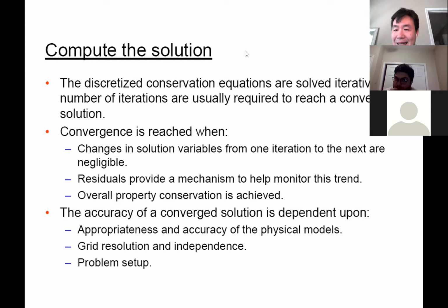But for the unsteady simulation, remember, nothing converges. The solution changes from time to time. So in some cases, it's unsteady, right? Like a weather forecast, the weather pattern changes every time, every second. It won't be the same. So it's an unsteady simulation. There's nothing to converge there. Okay, remember this. Convergence is only for the steady state simulation.